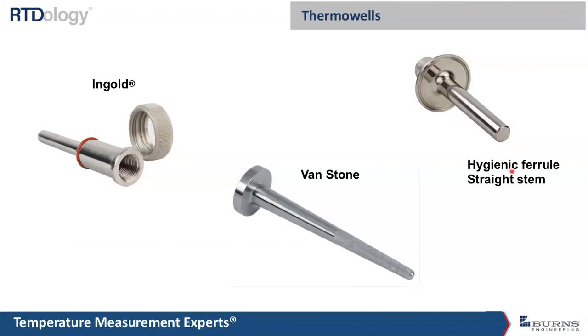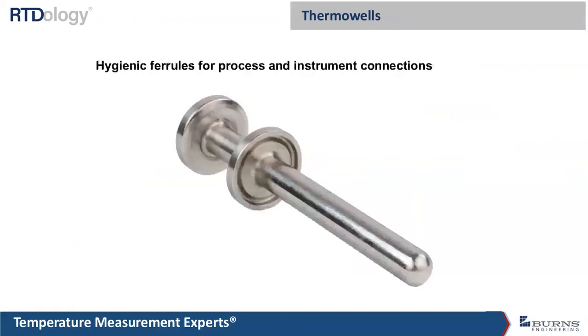And finally, for sanitary applications, there's a hygienic ferrule, sometimes called a tri-clamp fitting, which is an old trade name. This one's shown with a straight stem. And here is another sanitary Thermowell that has a hygienic ferrule for the process connection and also the instrument connection.